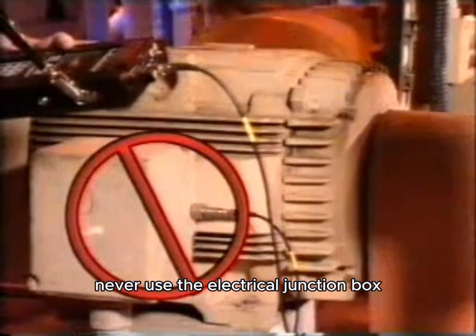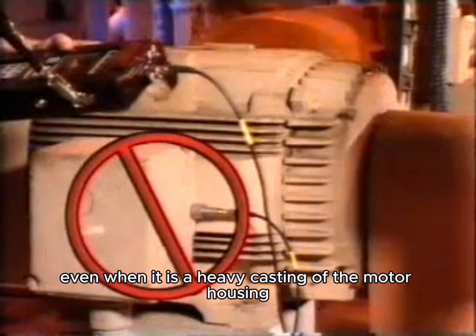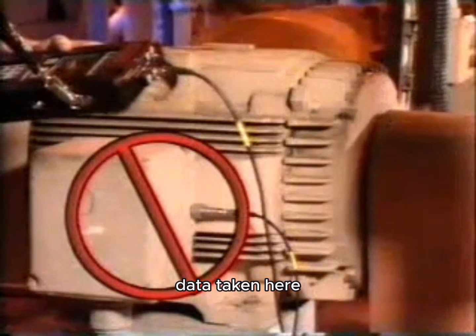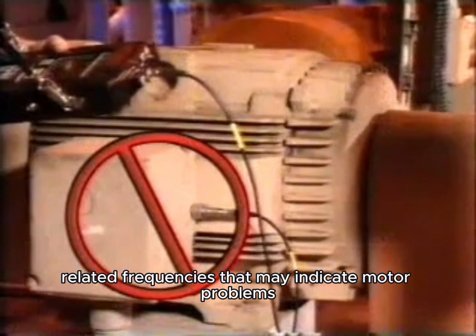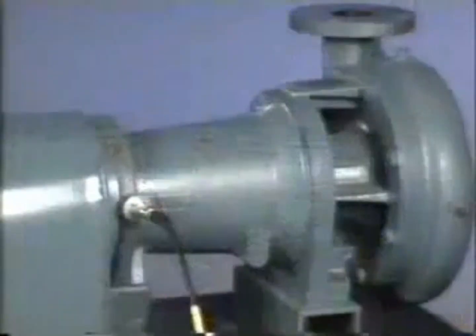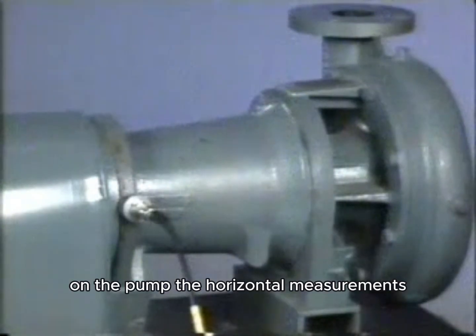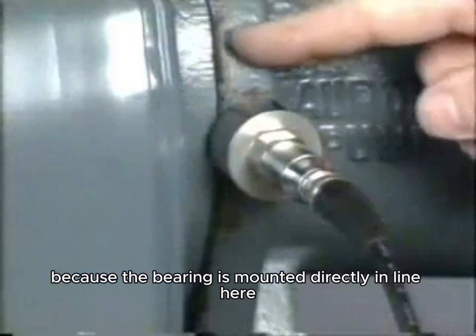Never use the electrical junction box for an axial measurement, even when it is a heavy casting of the motor housing. Data taken here will have higher levels of electrically related frequencies that may indicate motor problems that don't really exist. On the pump, the horizontal measurements should be made on this flange because the bearing is mounted directly in line here.